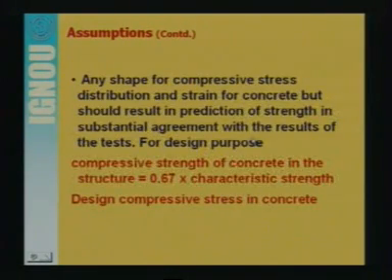0.0035. The next assumption is that we can assume any shape for the compressive stress distribution and strain for concrete. If we look at the stress strain diagram of the concrete, what should be the shape of the stress strain diagram of the concrete? As we know, I just told you that the behavior of the concrete under loading is inelastic from the very early stage of the loading.